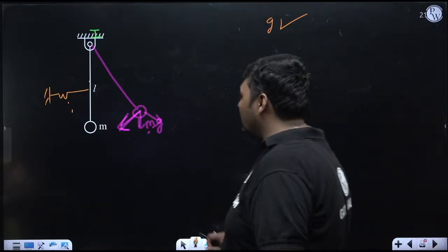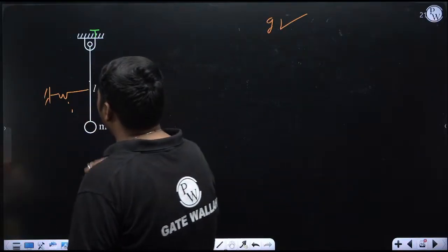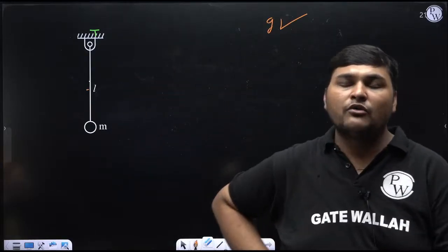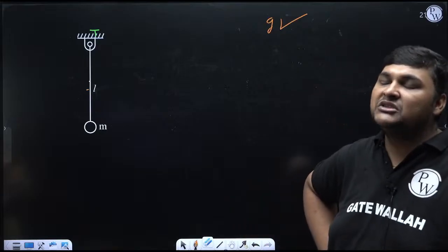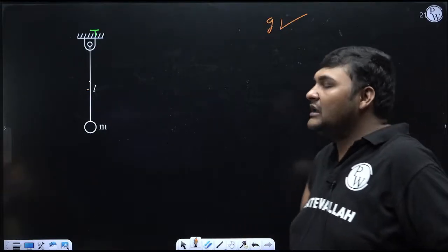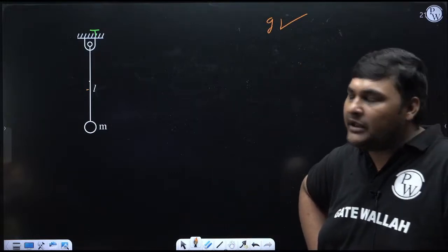And how? For a rod you can remember, whenever a vertical rod is hinged at any location like this, whether a spring is present in the system or not, there will be a role of gravity or weight in the restoration. And when we derive the equation of vibration, we will consider weight also. Simply see, at the mean position, due to weight in the spring, if the spring is present, think whether static deflection will be present in the spring or not.